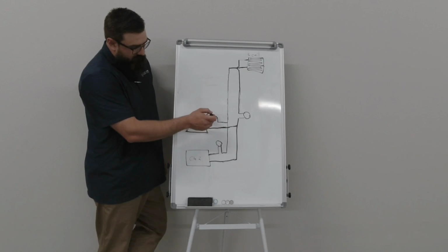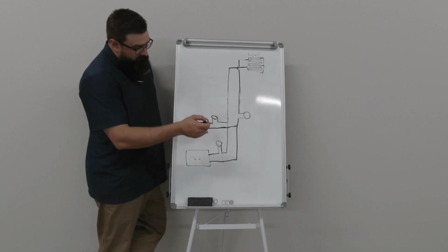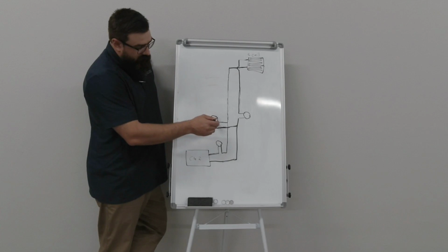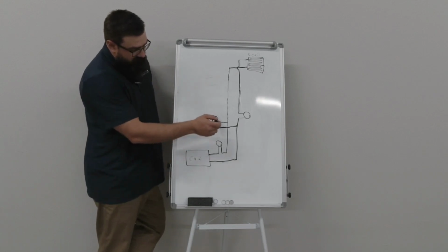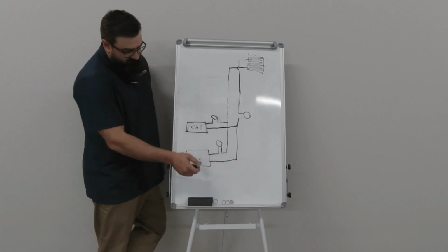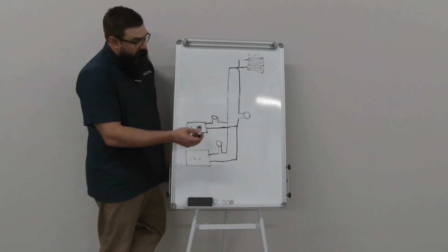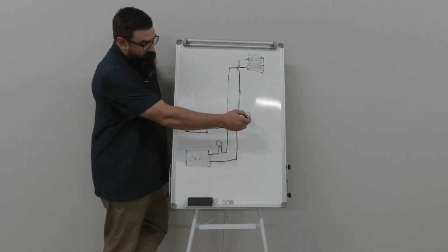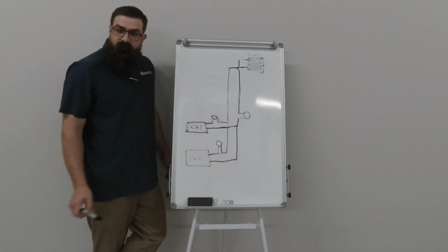primary pump. Bypass though. Well, or a bypass valve. And then that pump can stay at its most efficient rate for that chiller. And then you can vary your building flow with this guy.